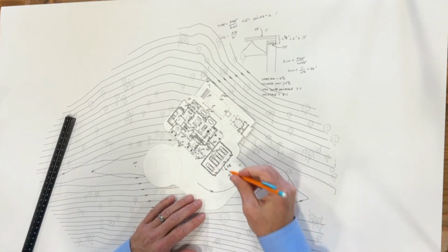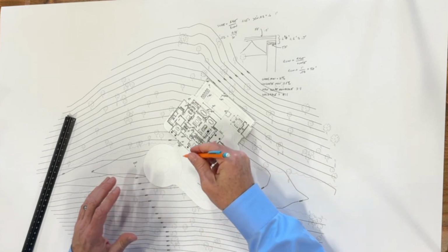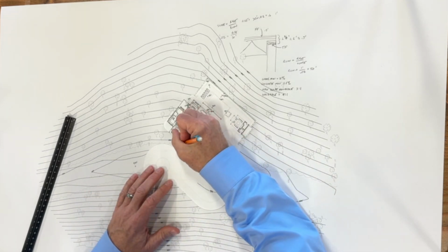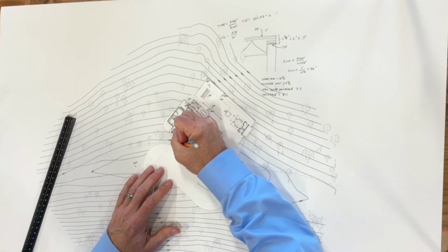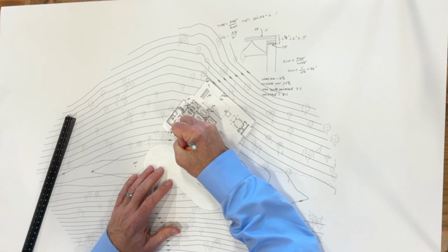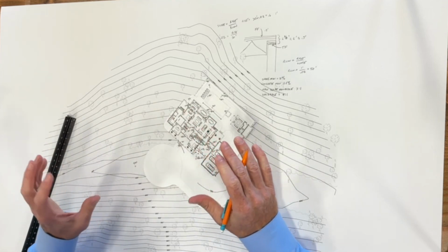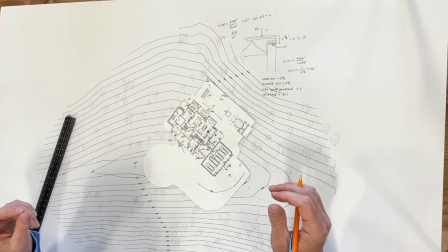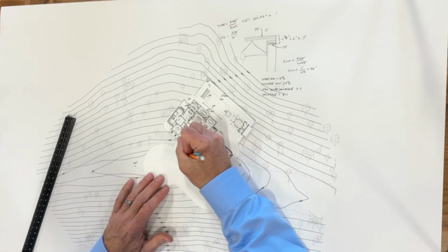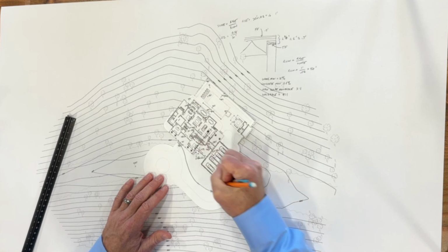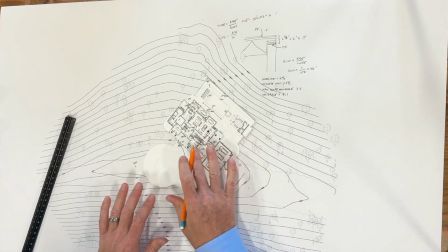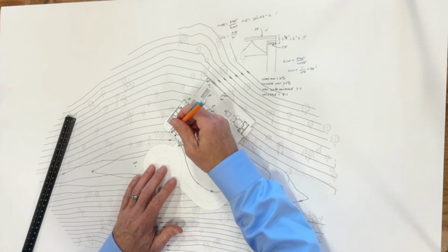Okay, so all right, so I got a 941 house. There's my 940. Now we also notice the 940 is all the way up by the house right there, right? So that means this guy has got to come in and attach. By the way, the contours always have to meet. They can never end because that would be physically impossible. So it has to connect. It's like a Tetris game or a puzzle game. So I'm going to kind of slope it like that. So there's that flat area that comes over there, right?